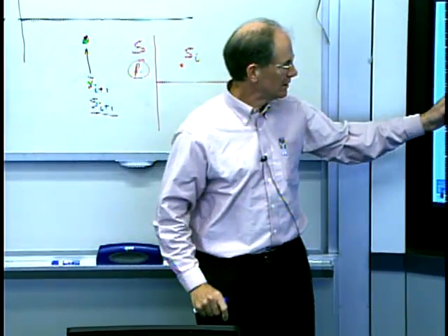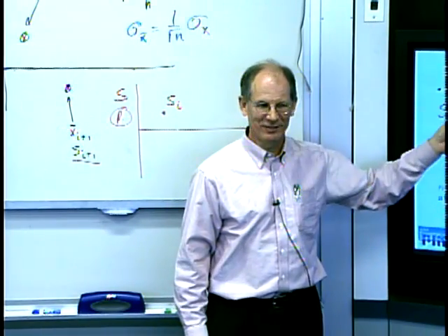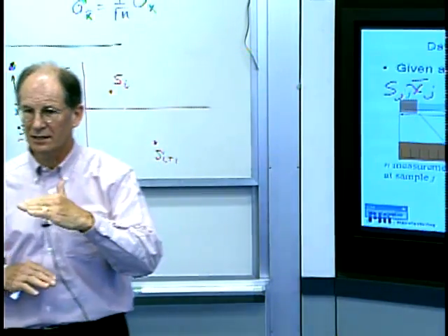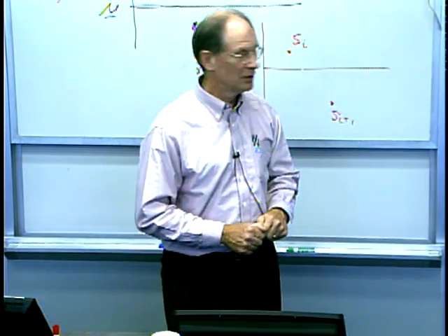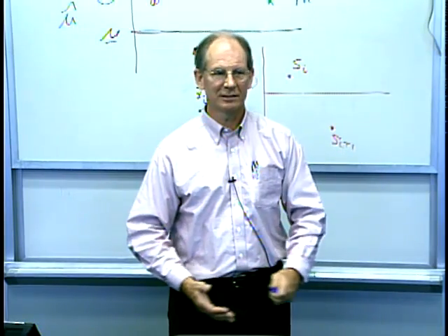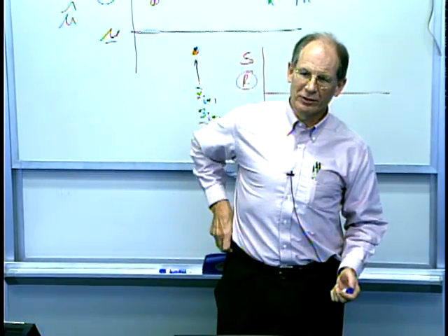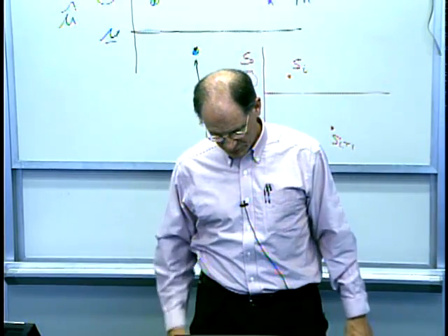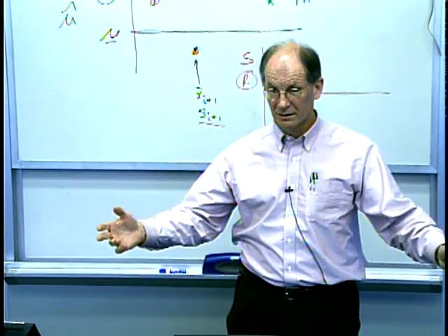There's a cost to every measurement we make, and a cost to every average that we take. In the past, those costs could be pretty high. They're tending to be much lower these days with automated inspection and things like that. But yes, there's a cost-benefit tradeoff. So if it's a part where it's not that important, if you look downstream and you say it's not a key characteristic of the product, it can vary.